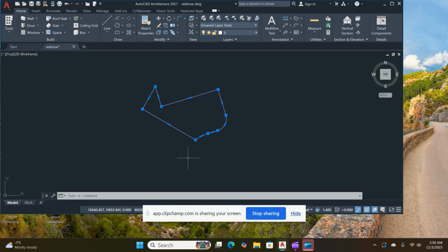This concludes the reconstruction of the side of the surveyed property boundary in AutoCAD, completed using bearings, distances, chord bearings, chord lengths, and radii. In this session, we reviewed the survey document, configured drawing units, standardized annotation fonts, and constructed all straight and curved boundary elements in real time.